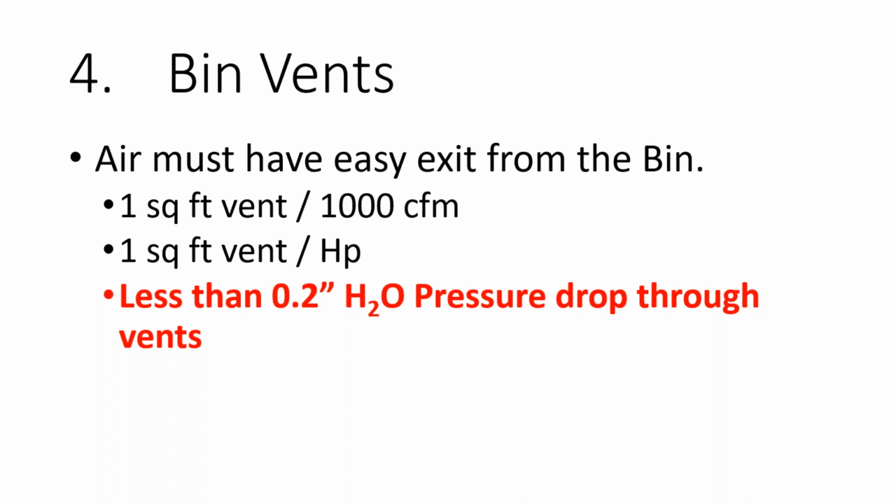And this is a luxury that you do have when you have an IBD monitor, because you know exactly what your delta P is with your vents. I'm not saying that 0.2 inches is the only number. Really, my choice of 0.2 inches is a statement that I want it to be low.